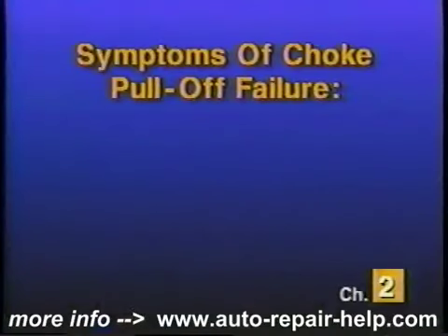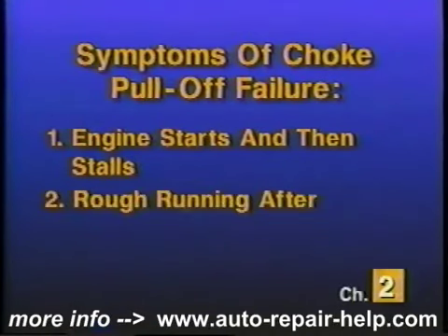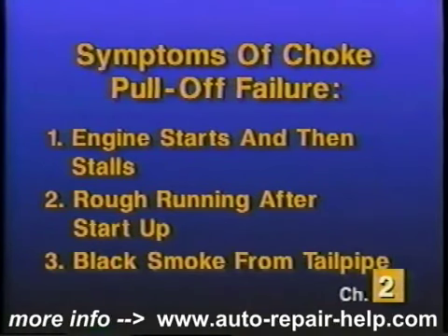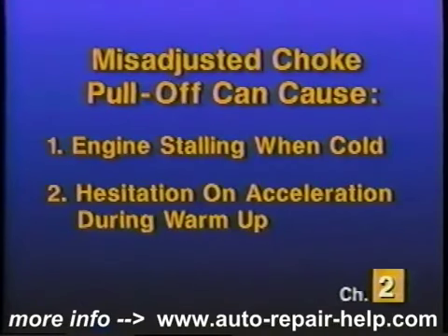Symptoms of a choke pull-off that has failed include an engine that starts and immediately stalls, rough engine operation right after initial startup, and black smoke from the tailpipe during cold engine operation. On the other hand, a misadjusted choke pull-off, one that opens the choke blade too far after initial startup, would cause engine stalling when cold and a hesitation on acceleration during the engine warm-up period.